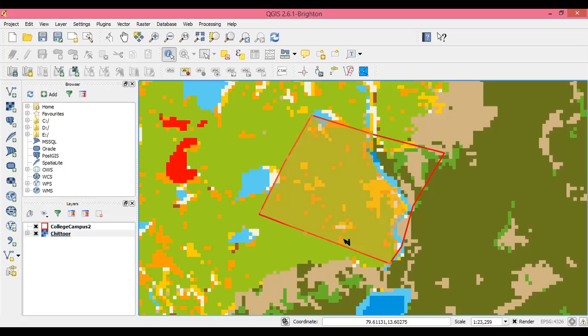By this technique, you will estimate what the average runoff coefficient of the college campus is. Okay, so that gives you the C inside your equation Q equal to CIA, right? A, you know what it is. A is the area of your campus, no problem.